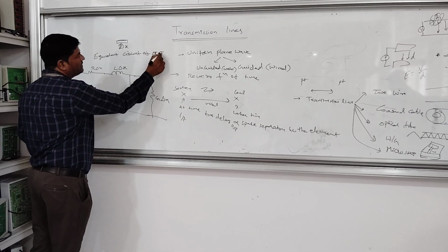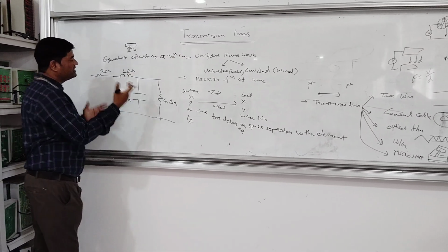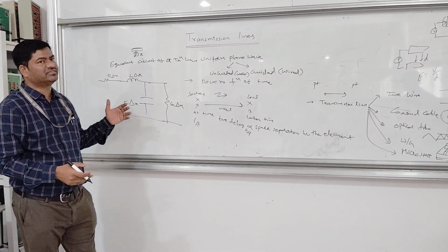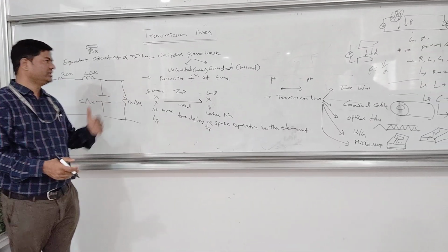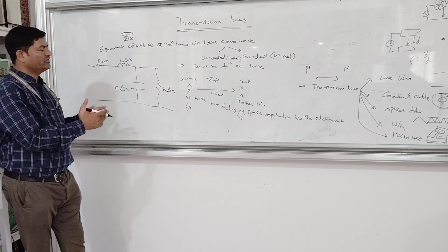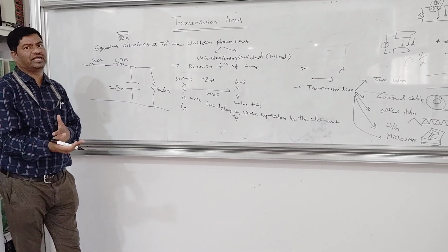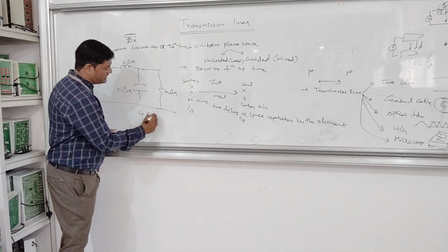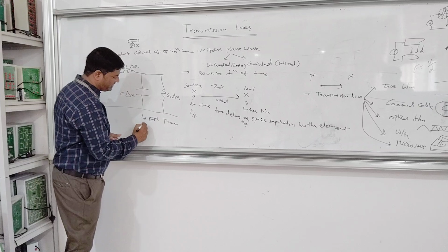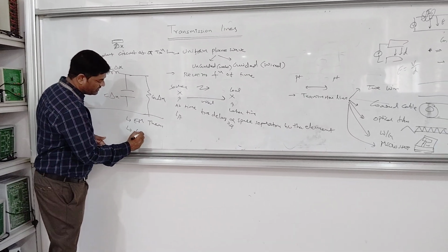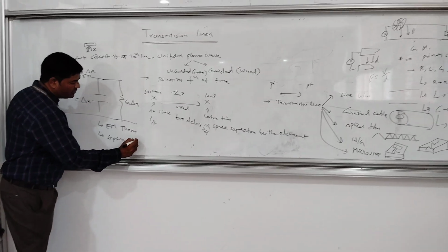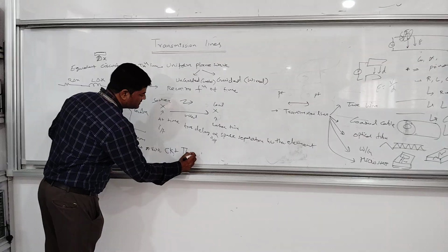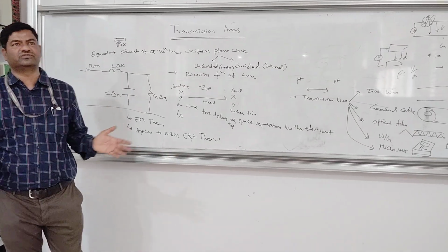of a transmission line. And from this, what is the conclusion? These are distributive in nature, and that is the reason we call these elements distributive. These are very important parameters for how the line behaves and how we will analyze it. That is the only reason that, instead of using EM theory to analyze all these parameters, for simplicity we go with circuit theory. If you know KVL and KCL, it is good enough.